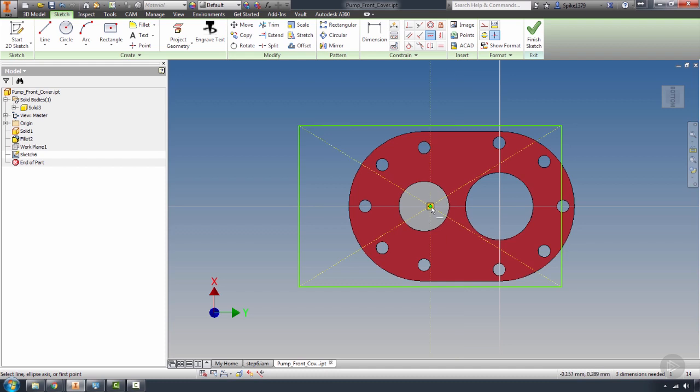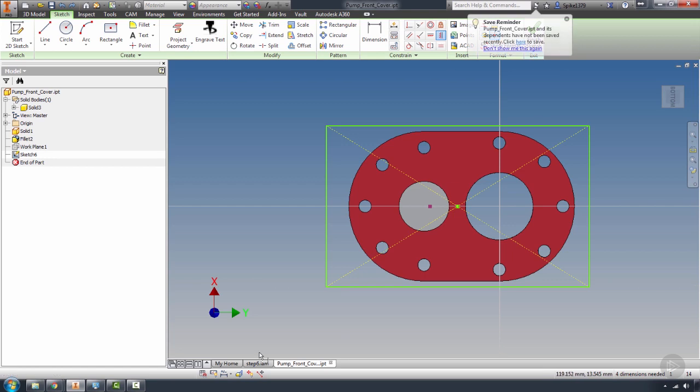And you can see that that's actually the wrong constraint because I'm actually flipped from my XY. That's not a big deal. I can just hit Control Z and undo that. And I actually want to make this a vertical constraint. In the Y direction is my vertical plane at this point. So I'm going to grab the points.